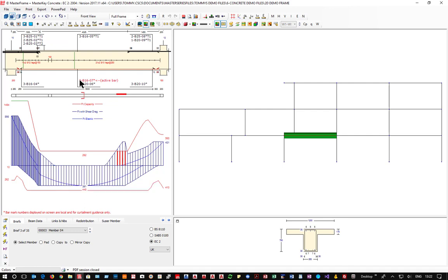So all I'm needing to do is to use my mouse and left and right click to increase, decrease or remove. So left mouse increases, so 320s or 420s. 416s isn't going to do it. They are probably wanting to use 3 bar arrangements. So down to 3, up to 20s, and we're just working.